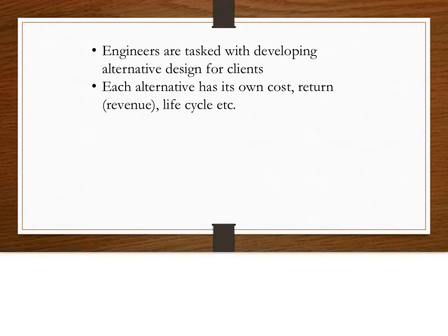Alternative 2 would be, say, an earthen dam, which is relatively cheaper to construct since it doesn't require any skilled labor and uses inexpensive materials. However, the earthen dam will need much more maintenance to repair parts of the dam that erode away, among other things. Also, the design life is going to be much shorter.